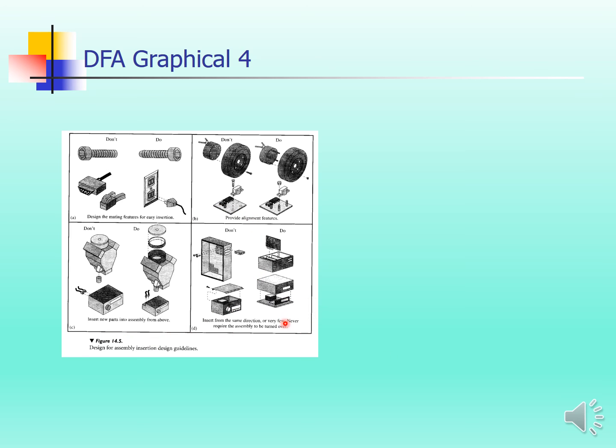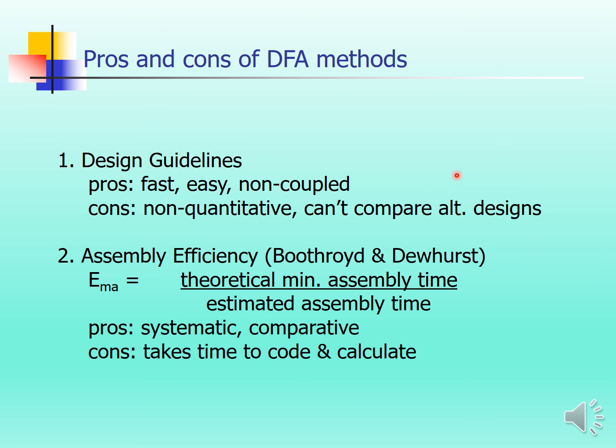This idea of design for assembly is to reduce the time for assembly. Then we have what we call Poka-yoke, which is very important. Make sure your part cannot be inserted in reverse rotation and so on.